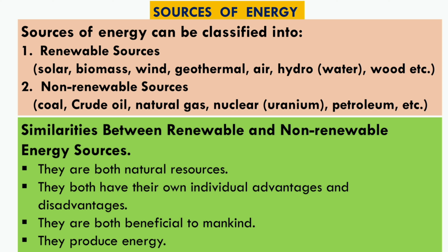Coming to another source, atomic energy. A tremendous amount of heat energy is liberated by fission of uranium and other similar fissionable materials. It is estimated that 1 kg of nuclear fuel is equivalent to about 2500 tons of coal. The heat energy liberated in atomic reactors is extracted by pumping a fluid or molten metal like liquid sodium, or gas, through the pile. The heated metal or gas then exchanges its heat in the heat exchanger by circulation. In the heat exchanger, the gas is heated or steam is generated, which is utilized to drive a gas or steam turbine coupled to the alternators, thereby generating electrical energy.